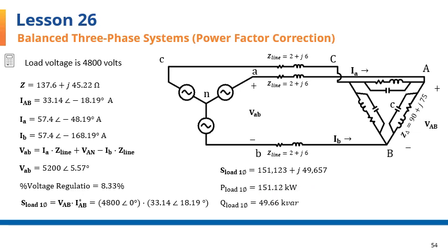From that, we can find the real and reactive powers of the single-phase combination of load and capacitor. Real power is the real part of the complex power, and reactive power is the imaginary part of the complex power. I just converted them into kilowatts and kilovars.